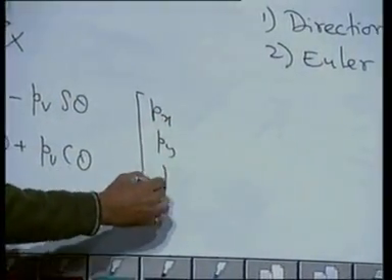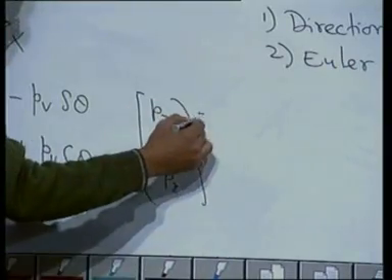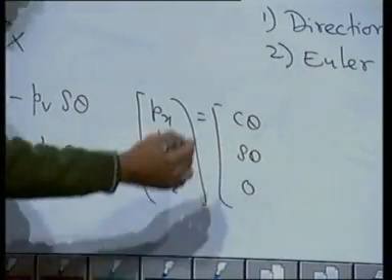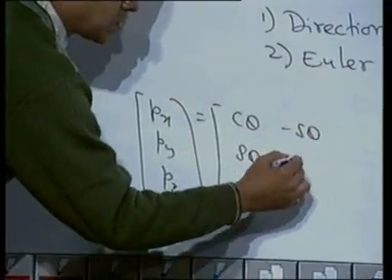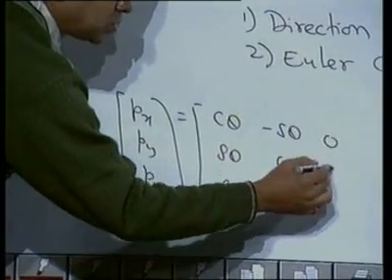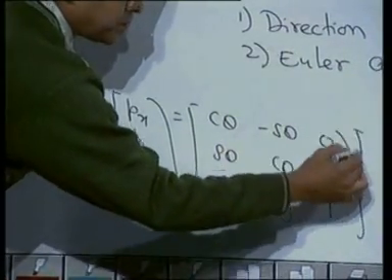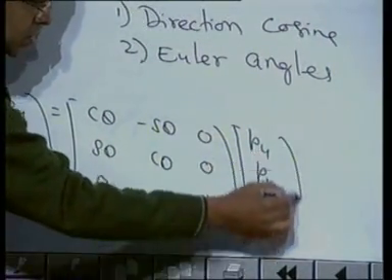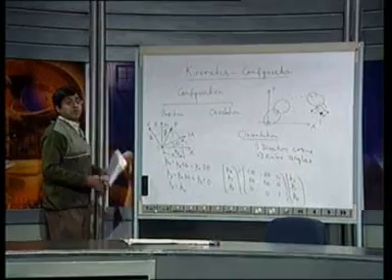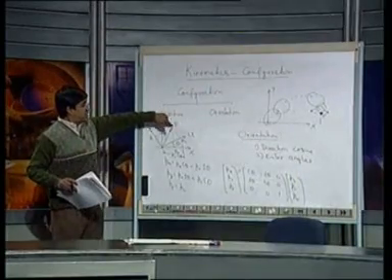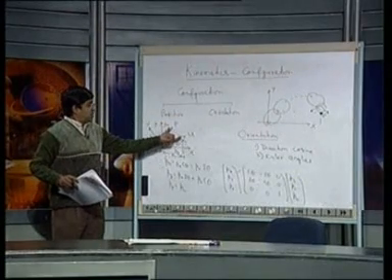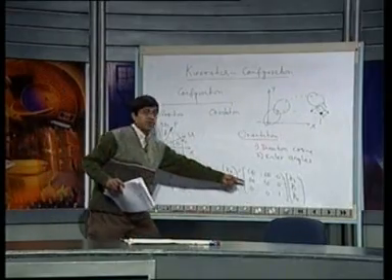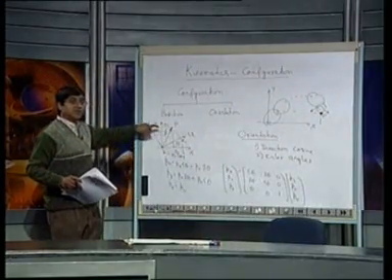We want to now put it in a matrix vector form, and then you will see this is cos theta, sin theta, 0; minus sin theta, cos theta, 0; 0, 0, 1, times P u, P v, P w. So, effectively what we got is the representation of this vector shown in this frame, and by multiplying this matrix we get its values in the fixed frame.